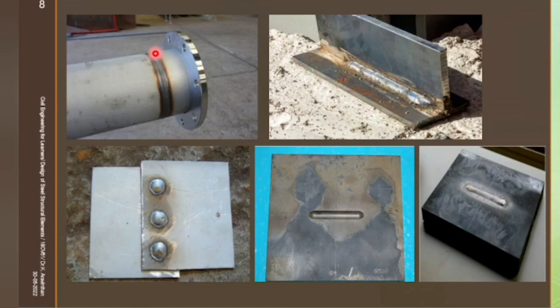What is this kind of joint? So you know 4 types of weld right now: groove, fillet, slot and plug. This is groove weld. Why? Because you have a weld but it is not projecting outside, it is connected within the material. You can see that there is no junction or there is no angle, and you are connecting at that member. It has been cut at this point and it has been made. What is this type called?